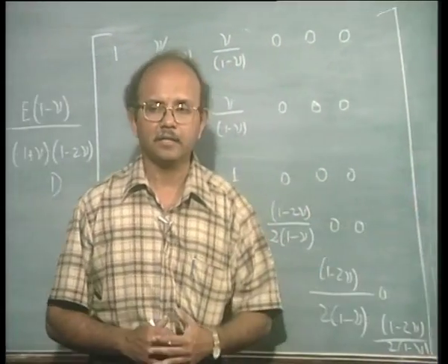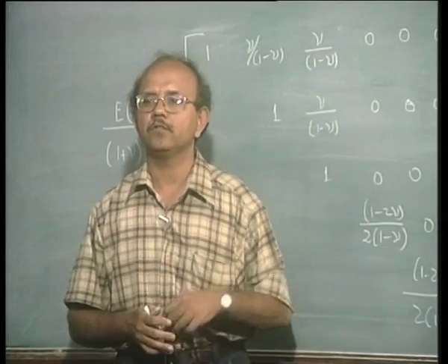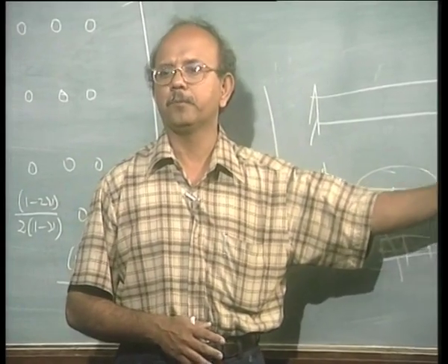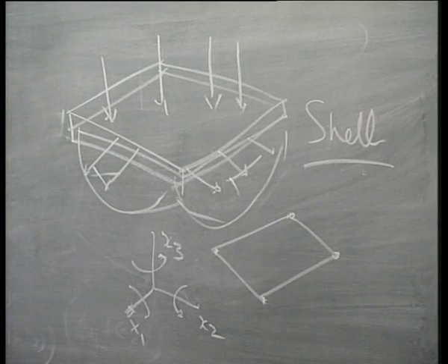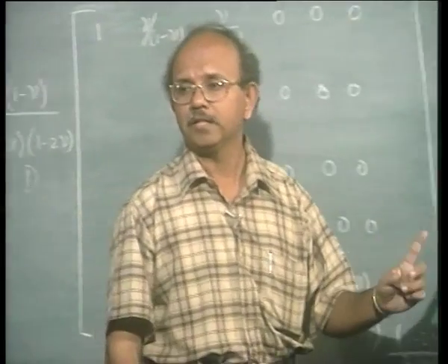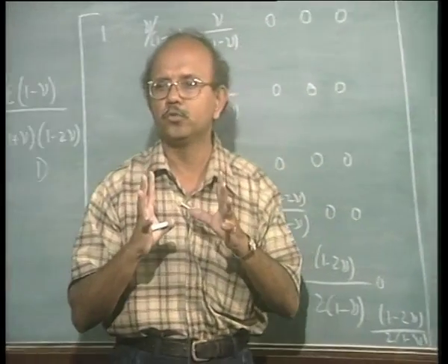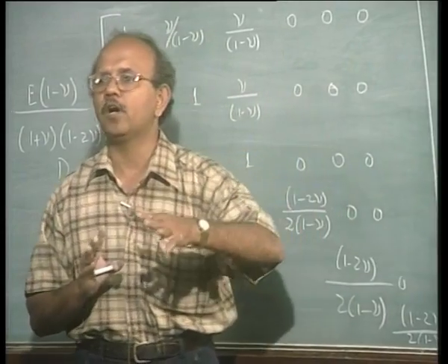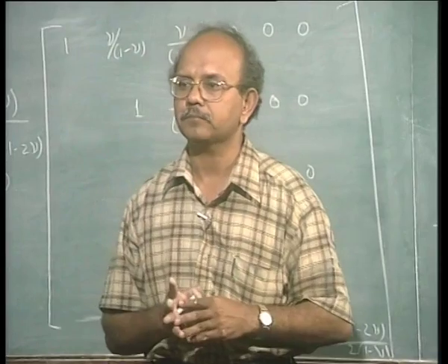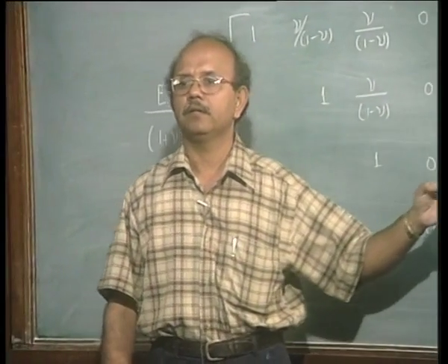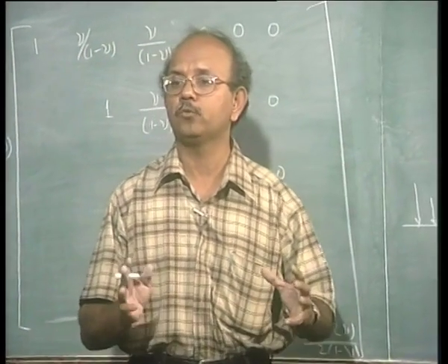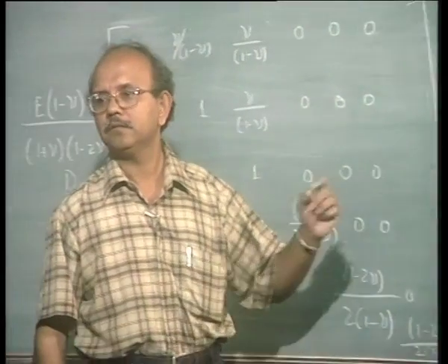So usually we cover shell theory and shell elements only in advanced classes. We do not usually introduce it at a lower level class or in the introductory class because it is not very easy to understand. If time permits, later in the course, 1 or 2 days, I will just highlight the issues and the approaches towards the element formulation for shell. But that does not mean that you will not use shells. As long as physically you understand what a shell is and how to use it, and right now get convinced that 6 degrees of freedom somehow people have put inside, it should not be an issue to use it in a practical case. Okay, hence that particular problem that you saw for the coach is modeled by means of what are the 2 types of elements, beam as well as shell element.